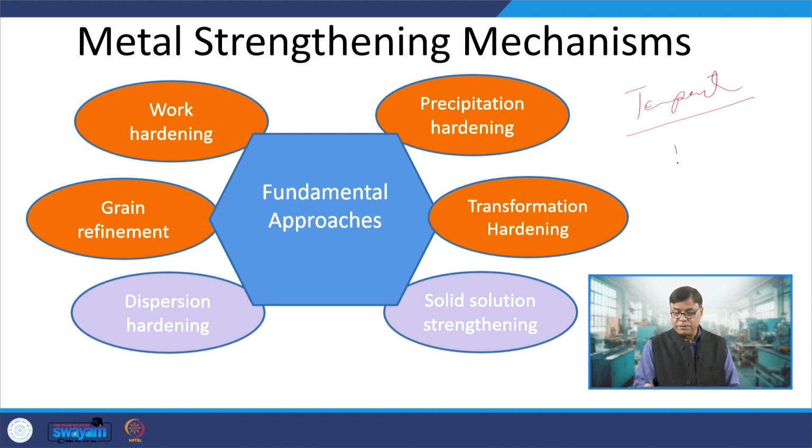At high temperature the work hardening effect is very limited. There is a possibility of dissolution and loss of the precipitates. So, there will be a decrease in yield strength due to recovery, recrystallization, loss of the precipitates, grain coarsening at a high temperature, and then a possibility of the formation of soft phases.